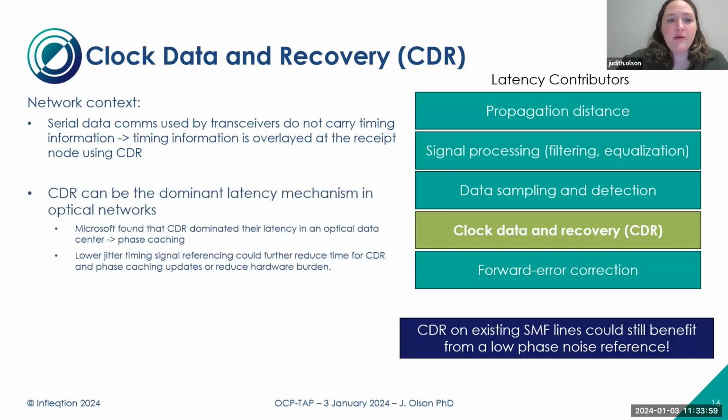But generally, it was found to be a dominant latency mechanism, particularly within a data center that is using optical processing. So Microsoft found that CDR actually dominated the latency in many of their different data centers out there. Most of their messages were really, really short, but each time you sent a message, you had to redo the entire clock and data recovery process. So it ended up being really time consuming, taking up the vast majority. I tried making a pie chart of this, but it was almost all clock and data recovery with really tiny slices for everything else. So I went back to just listing it.